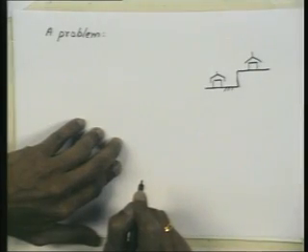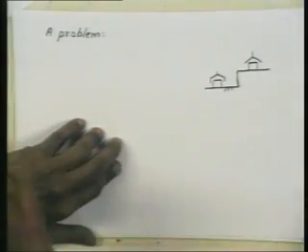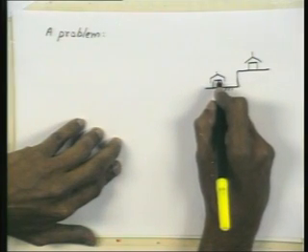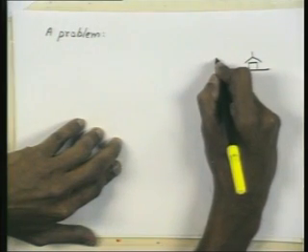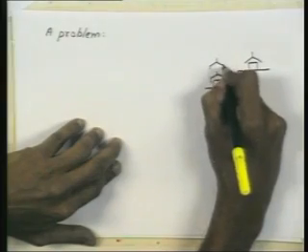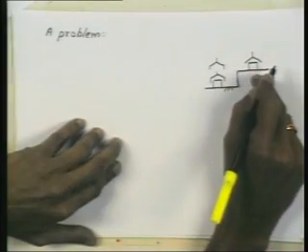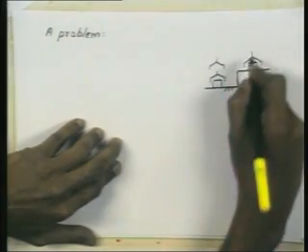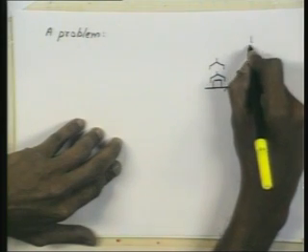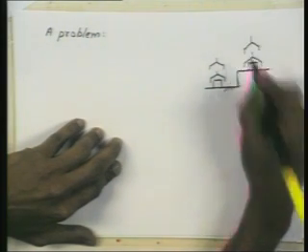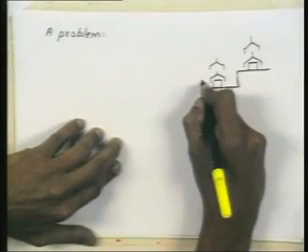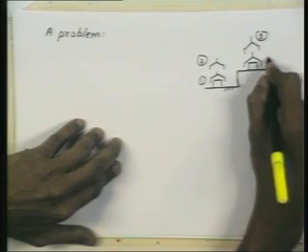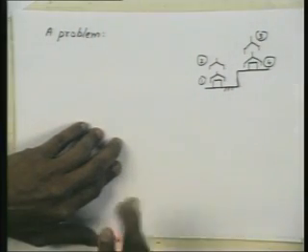Fine. Now in order to ensure that this is taken up and not into the table, into the surface, we may say that immediately after this it has to go up, so maybe to a position like this. And before it is put down, to ensure that it doesn't hit the corners, it has to be taken up like this, and so we will specify some position here, so that this could be the first position, second, third, and finally we put down the block and release it.